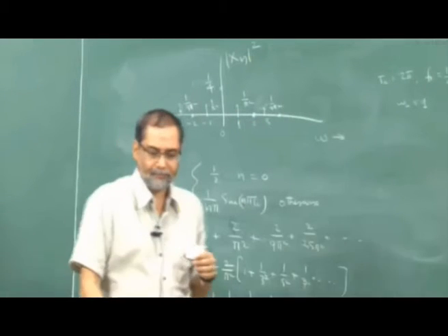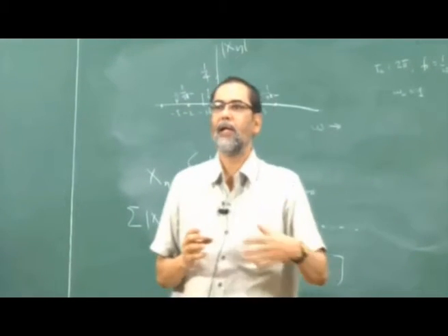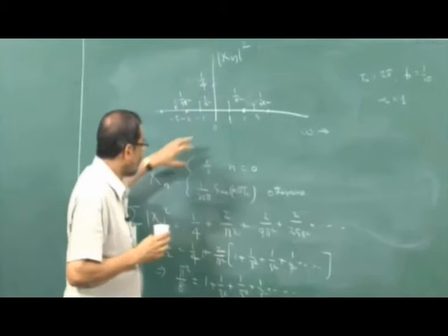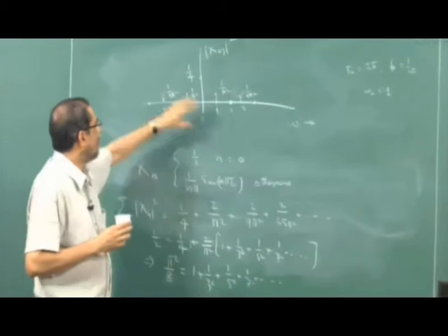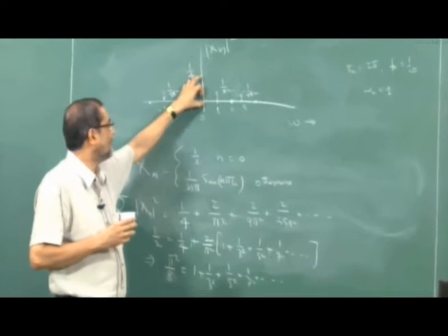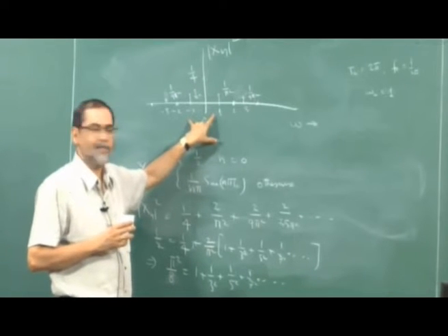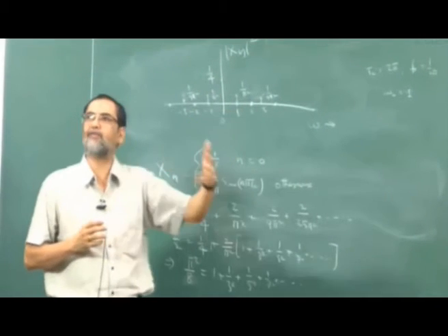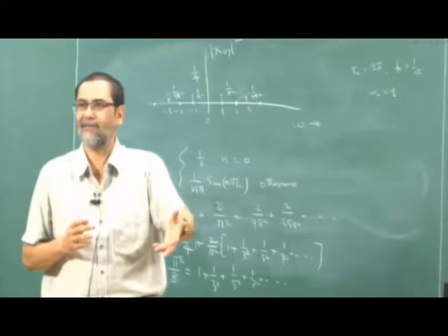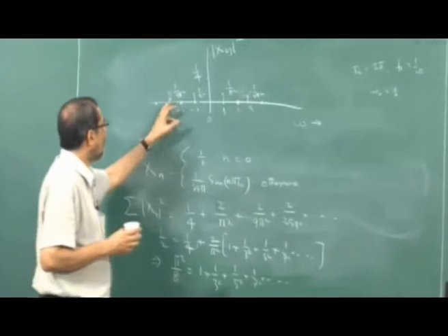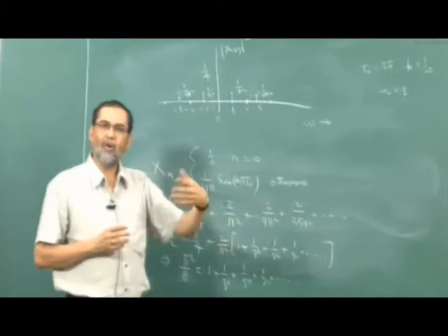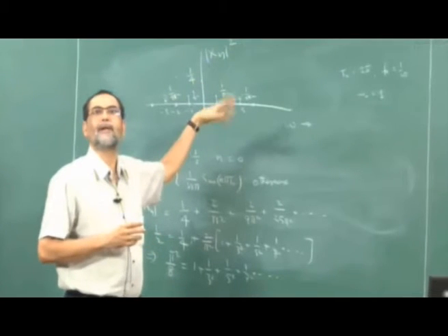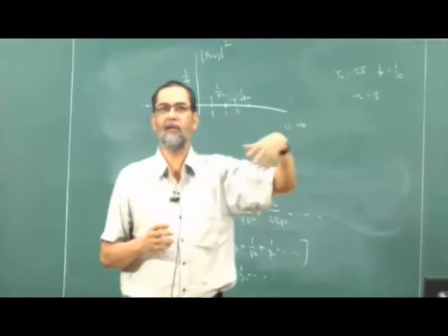So the power spectrum tells me how much power is contributed by each of the complex frequency terms. The total power in the given signal is half, of which 50% is present in DC itself, and the first harmonic or the fundamental frequency contains a significant amount, 0.1, 0.1. So 0.25 plus 0.1 plus 0.1 is already 0.45. Total power is 0.5, so I'm already closing the gap, and all even terms contain 0 power, all odd ones contribute some power, and they contribute less and less as the frequency increases. So this is the power spectrum, which tells me how the power is distributed over various frequencies.